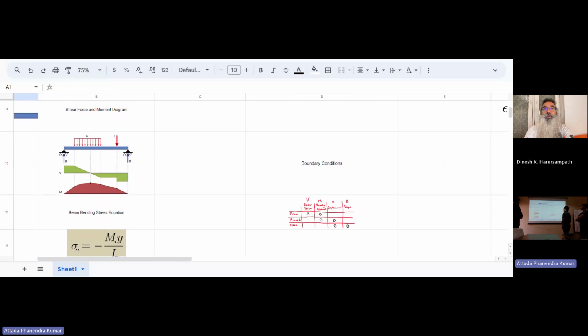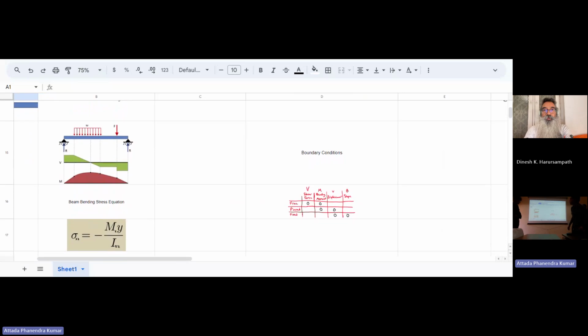Maybe what we're showing is just the relationship between applied force, shear force, and moment, and how they're all basically the integrals of each other. So you can start off with just an applied load. You can translate that all the way down to a moment. This is going to be a bending moment, which can also be translated into stress using the equation we have below, where I is the second moment of area in this case.